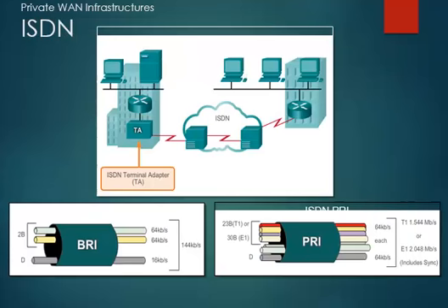Next, we'll have ISDN, that is, Integrated Services Digital Network. It's a circuit switching technology that enables the local loop of a PSTN to carry digital signals, resulting in higher capacity switched connections. ISDN changes the internal connections of the PSTN from carrying analog signals to time division multiplexed digital signals. TDM allows two or more signals or bit streams to be transferred as subchannels in one communication channel. The signals appear to transfer simultaneously, but physically the signals are taking turns on the channel.